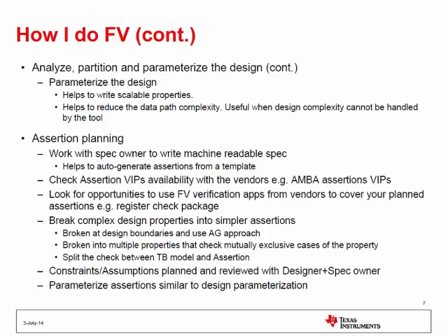Another important thing, and one of the main pitfalls of formal verification, is that we tend to write a lot more constraints and assumptions, and if you don't have a very good way of verifying that those constraints and assumptions are indeed correct, you will actually see that the completeness that you are getting is all lost, because you would have made a wrong assumption and you will actually miss a bug in your design.